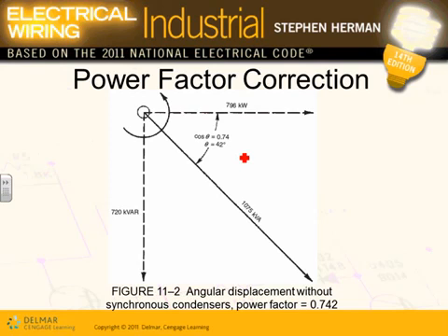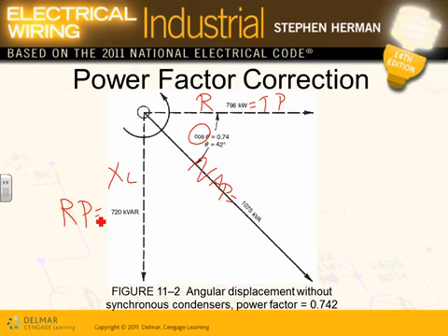Okay. The power factor, guys, is also the angle between the true power and the apparent power. This is the R, this is the Z, and this is the XL. This is the reactive power. Reactive power, true power, apparent power, R, Z, XL. Derek, you called it the power triangle and impedance triangle in the first semester. Power triangle and impedance triangle are exactly the same thing.